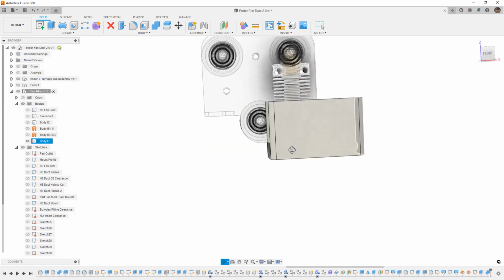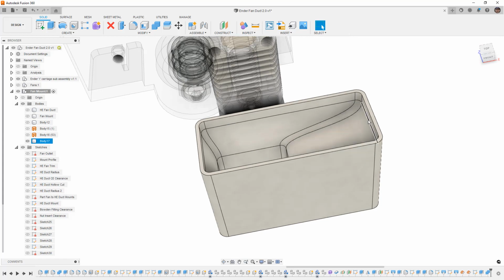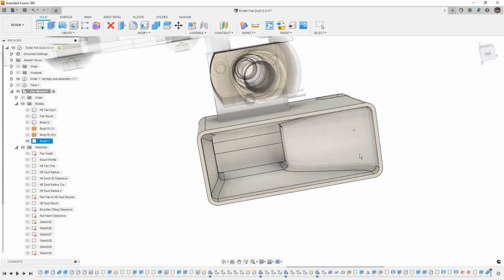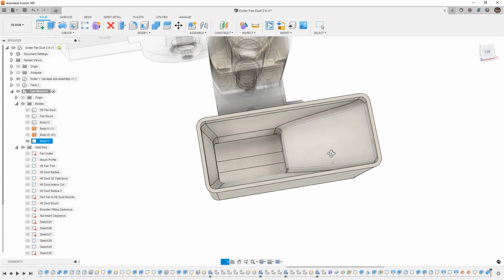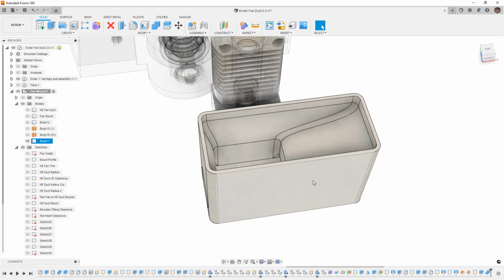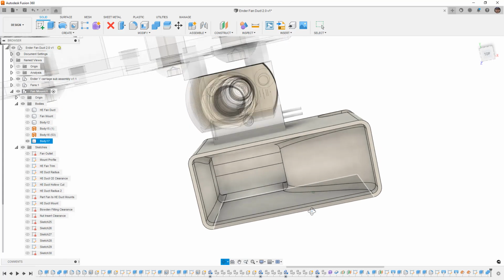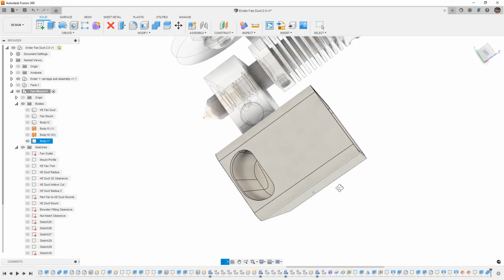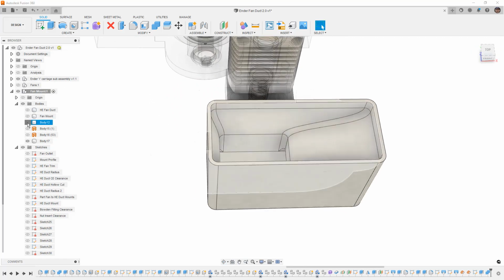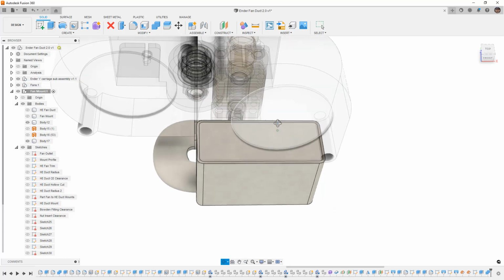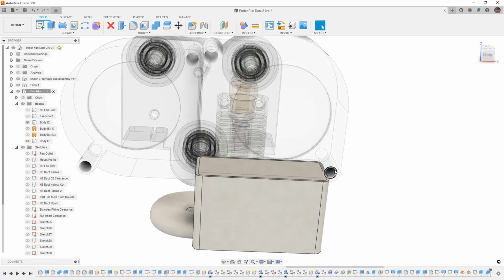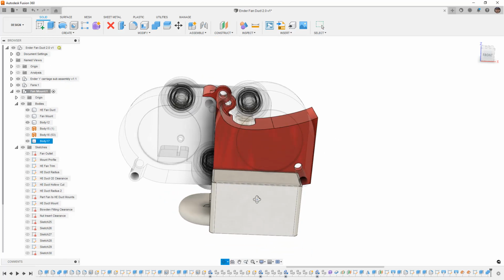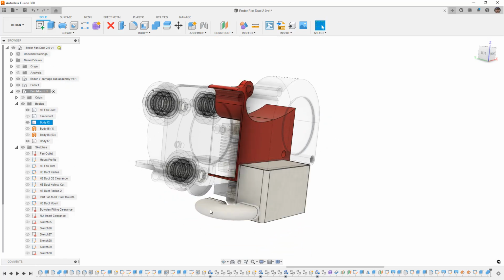Now again, if you're 3D printing this, the thickness doesn't really matter. Obviously, you could offset externally, you could offset the shape, but you could just do a 90% infill on this design, and anywhere that's over 1 millimeter, let's say, it's just some sort of infill shape. That way it would keep the part relatively simple to design, but you would still get the internal shape that you're looking for. This also lets you get away with building out complex tabs and features to mount to, say, the fan or to mount to something else without having to worry about all of the offset or the thickness or the shell.